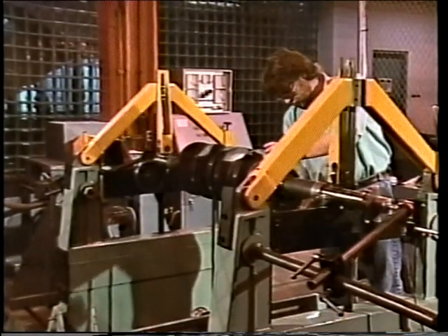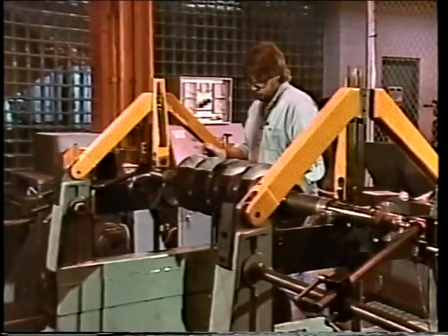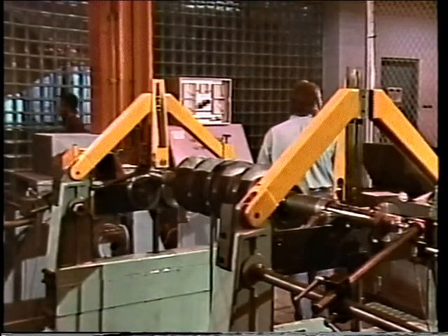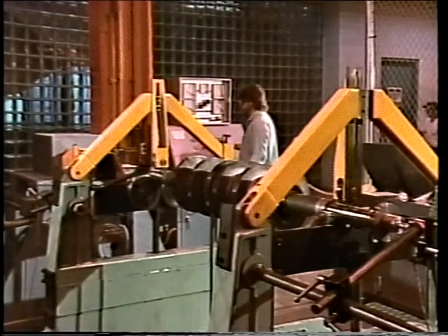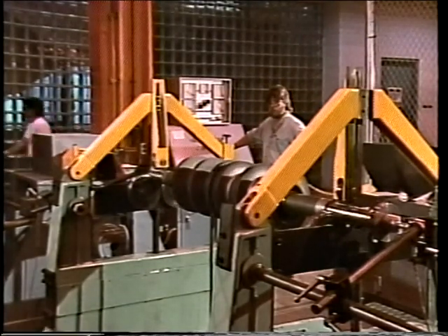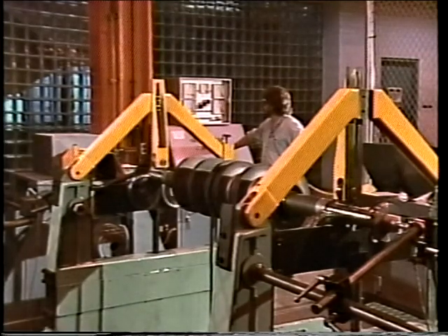Balancing the rotating equipment generally involves adding trial weights to the rotating element. Then, when the element is rotated, the phase angle and the amplitude of the vibration changes. These changes can then be used to adjust the weight so that the rotating element will be balanced.